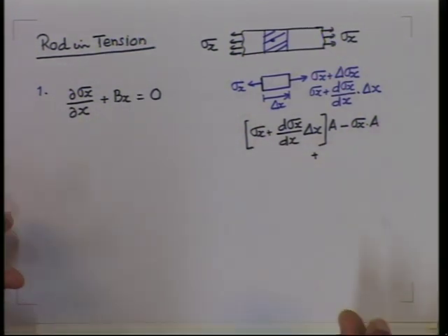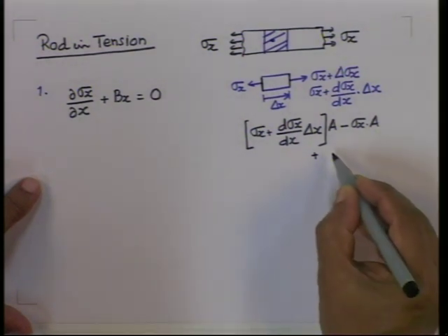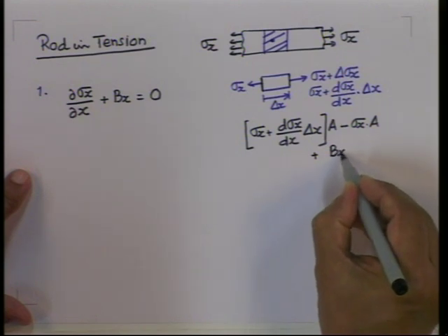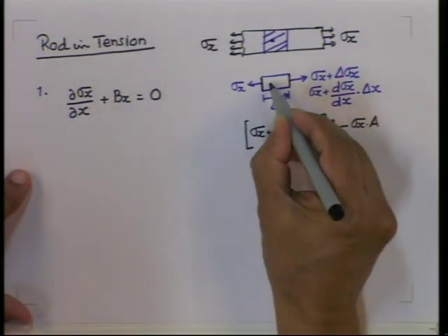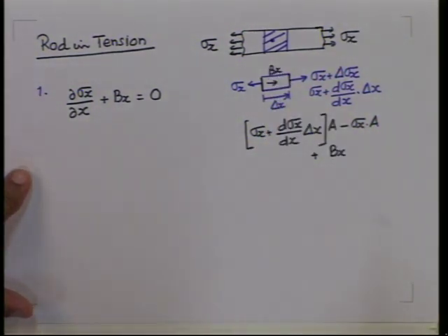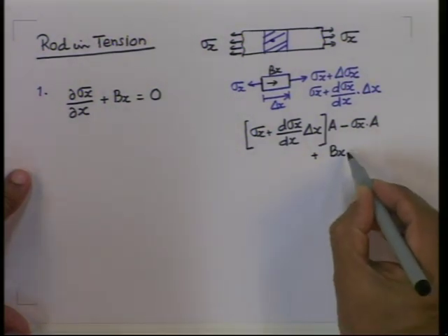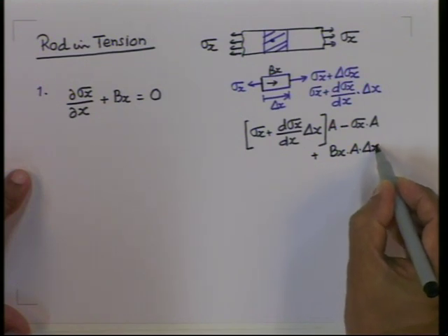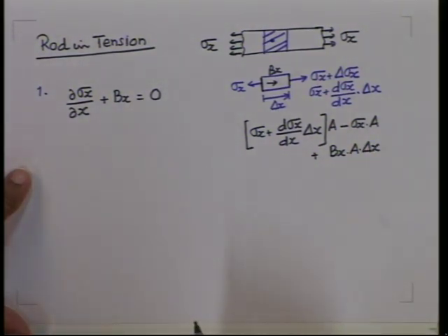So, in x direction, first of all you convert that into force. B x means self weight etcetera per unit volume, so multiply this by area into dx, which is the volume. So, this will be the total body force in x direction.